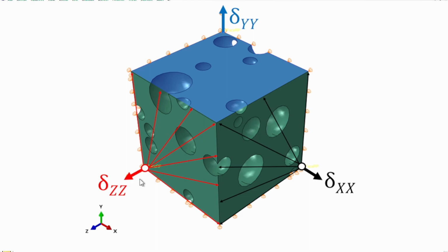Now the same thing applies with the z-axis. So again, if I'm tracking what's happening in the z direction, connecting this node, I then have to couple it with the whole face here, which I call my z front face. And the same thing will apply with the y-axis. The top face here is called the y top. So we'll demonstrate that again in ABAQUS.